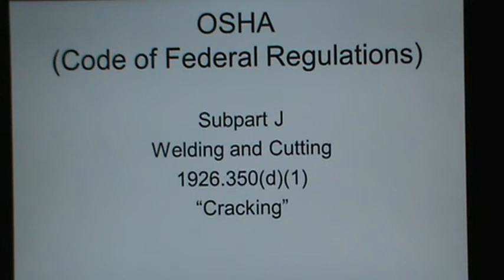Let's go to paragraph 350D1. They talk about a term called cracking, and that basically says you've got to pop that tank open a little bit. It says before a regulator to a cylinder is connected, the valve shall be opened slightly and closed immediately. This action is generally termed cracking. It's supposed to remove dust and dirt, that kind of thing.